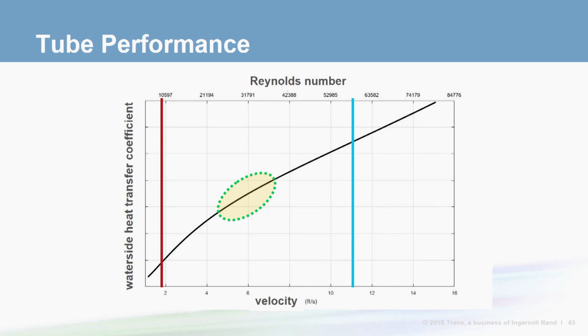When this occurs, it takes much colder refrigerant to deliver the desired chilled water supply temperature, thus increasing the lift on the chiller and the overall kilowatt usage. For the condenser side, the same situation occurs. However, you end up with a higher refrigerant temp as the tubes cannot efficiently transfer the energy from the refrigerant to the water.